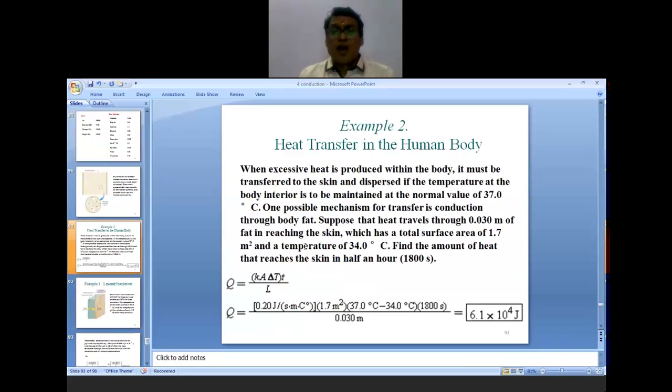So we can have these small problems that can also be asked in the examination, because I have put these small problems related to your basic equations, that is Q equal to UA delta T, Q equal to HA delta T, Q equal to KA dT upon dx, Q equal to m lambda. These are your basic four equations that are needed in case of heat transfer.